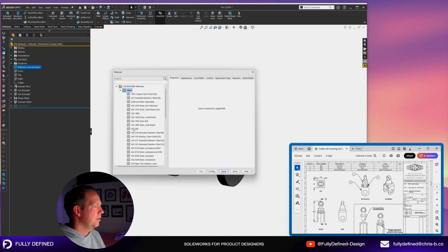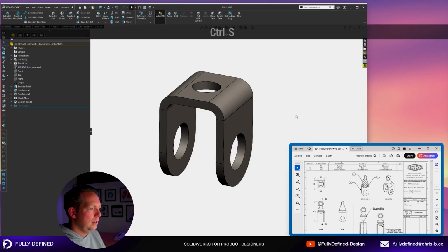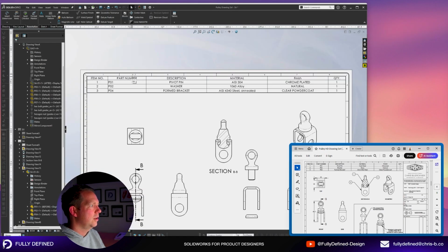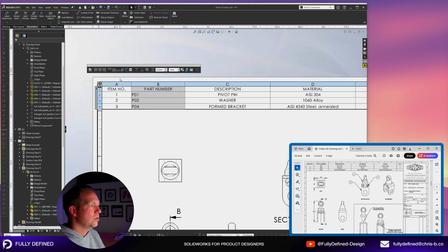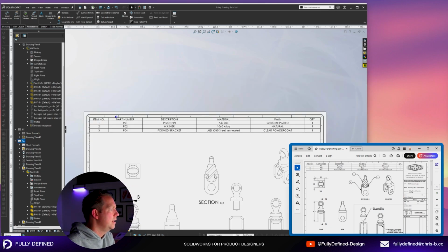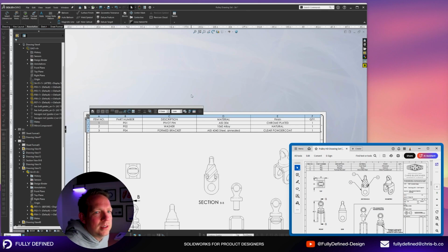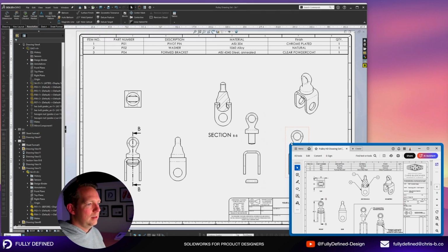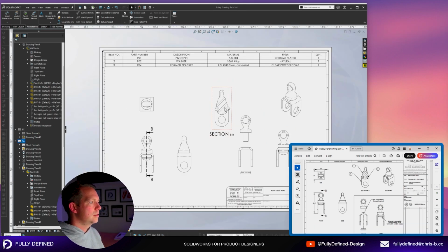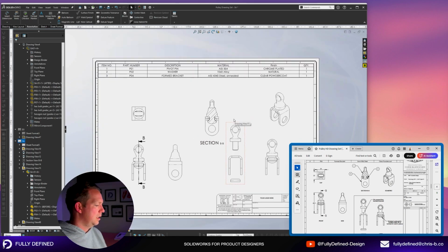The main thing about bill of materials is just that we're getting it on the page, identifying our parts and showing you the basics of how to edit it. Now you can do basic formatting changes as well, such as centering text, and you can also click and drag lines to resize. It can be a bit finicky, but you just want to get something that looks relatively like the drawing that we've got here, the example drawing. Okay, so that's the bill of materials on our sub-assembly.